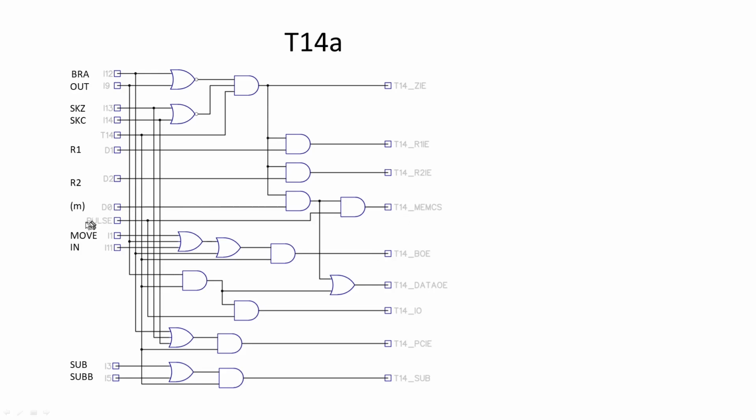And you've got a pulse. The pulse signal comes in here, and this is ANDed with the memory chip select signal here. And the idea of this is on actual memory chips, very often you can have the chip select turned on, and when the chip select is turned off, that's when the data gets strobed into the chip. So with the pulse off to start with, all the address lines and everything get set up, and the pulse comes on to chip select on the actual memory chip, and then when the pulse goes off, that strobes it into the memory. So you can use your memory chip select as your strobe into your physical memory chip or device.